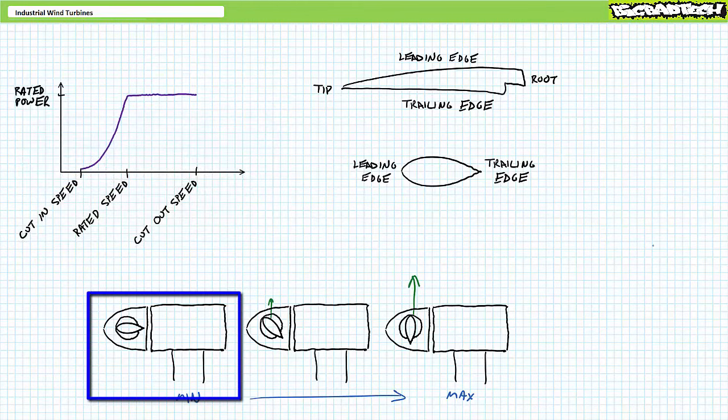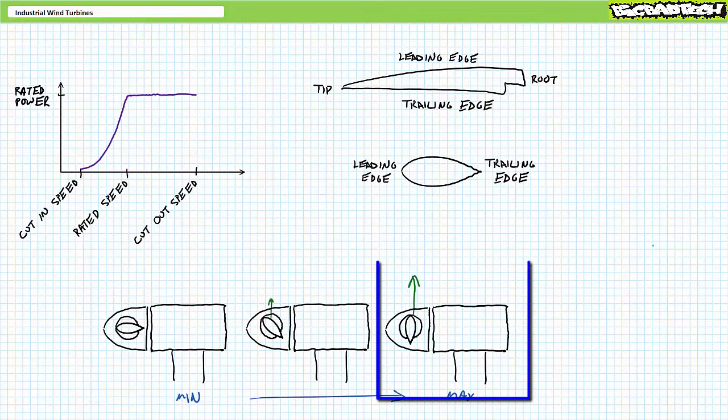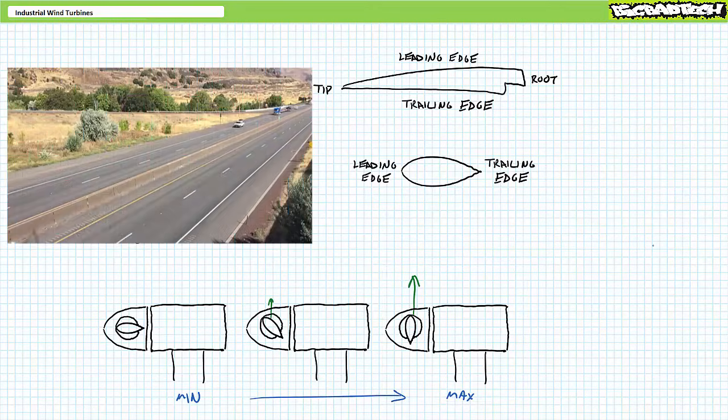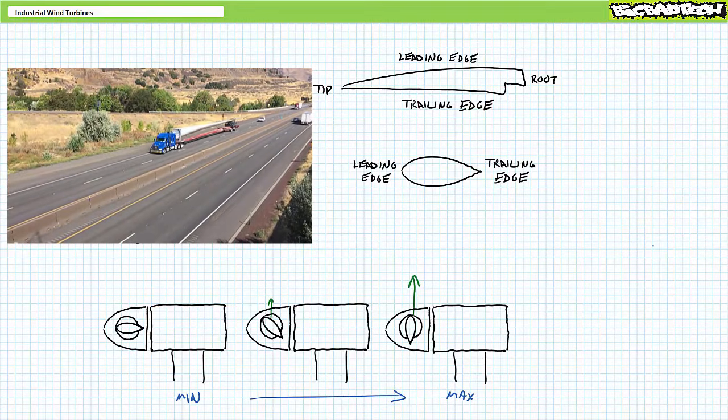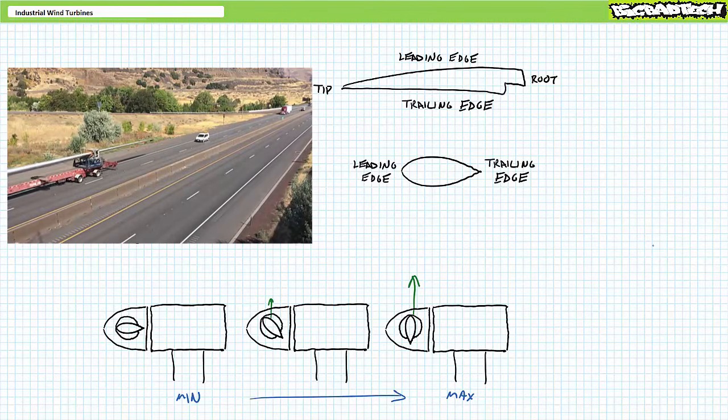When held at 90-degree pitch angle, parallel to oncoming wind, the blade cuts cleanly through and transfers no mechanical power to the hub. When progressively pitched back towards 0 degrees, the aerodynamics of the blade generates lift and transfers an increasing amount of mechanical power to the hub. A blade is not a simple construct as you might think, and sophisticated aerodynamic and mechanical engineering goes into its twist, profile, construction, and rigidity.